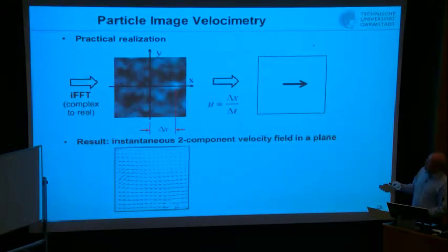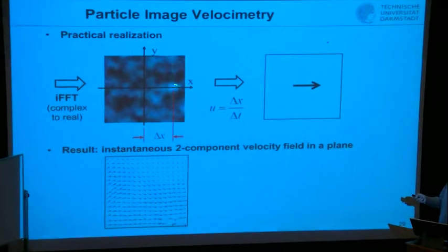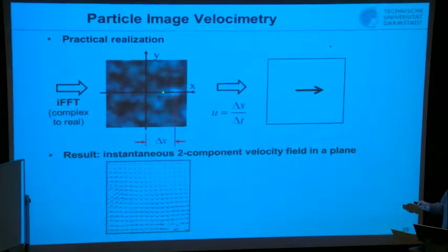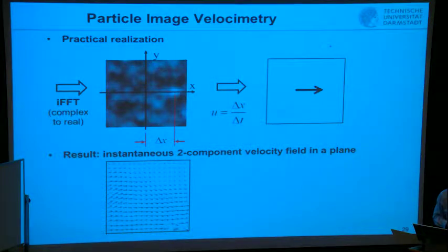So the idea is that, to have a sub-pixel resolution, you fit something like a Gaussian function over this correlation peak, and thereby you're able to reduce the discretization step size to something which is maybe a tenth of a pixel or so. And that is crucial because otherwise the dynamic range would be very, very limited.